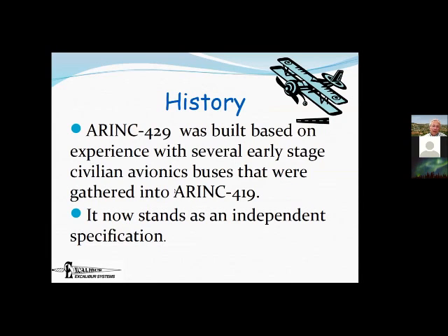Okay, now ARINC-429 itself was developed in the early 80s, and it wasn't developed in a vacuum. There was an ARINC-419 that came before it, and ARINC-419 had like a dozen different sub descriptions of buses. Most of them had in common that the major way of moving data was through a 32-bit word. They had multiple different